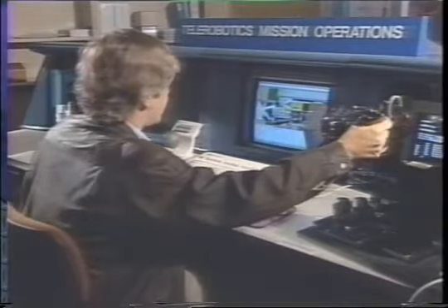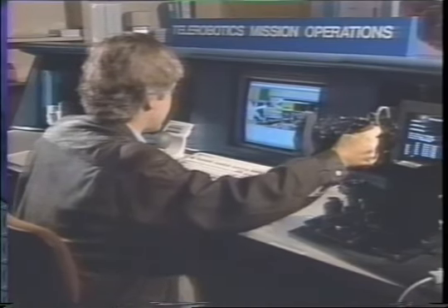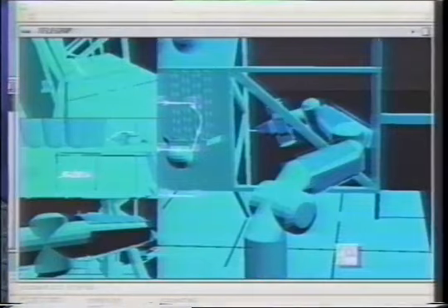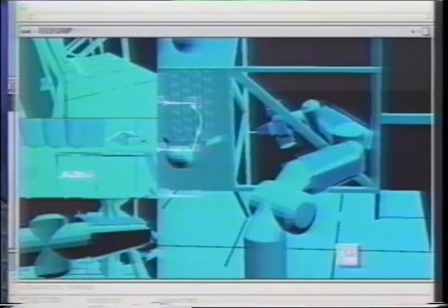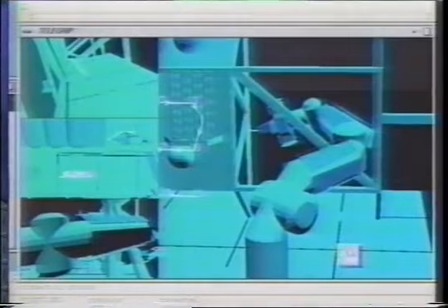Here, the operator modifies the position of the motion guide in simulation using a hand controller. The robot is constrained to stay on the motion guide. The motion guide is teleoperated into a position where the robot will not collide with the truss during the motion, and so that the view from the gripper camera at the end of the motion will be of a bottle hidden within the truss. The simulated view from the gripper camera is shown in the upper left graphics image.